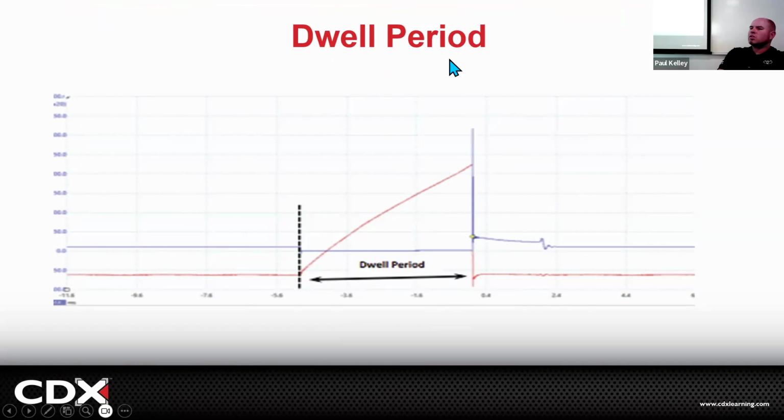It'll take more kilovolts to arc that gap because the gap is open, or because the spark plug is maybe really fouled with carbon or something. Exactly. We could say maybe it's open too much, but if you're really picking up what I'm putting down, we could scope this out and the height of this line can tell us if there's a problem like that. Rather than tell the customer you need to put spark plugs in it, we can actually measure it.